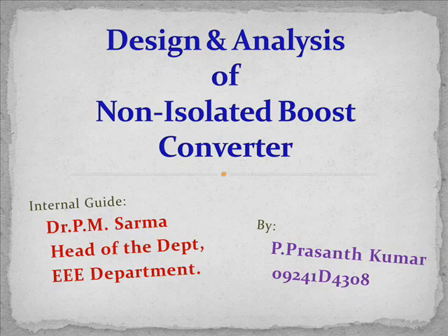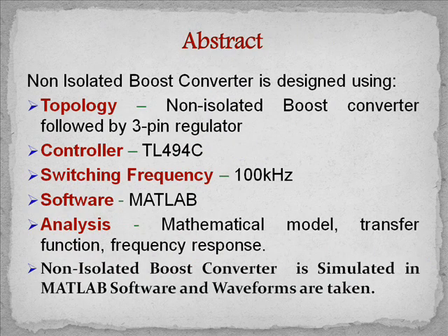My project title is Design and Analysis of Non-Isolated Boost Converter, and my guide is Mr. P.M. Sharma, Head of the EEE Department. The Non-Isolated Boost Converter is designed using the Non-Isolated Boost Converter topology followed by a 3-pin regulator. The controller used here is the TL494C, and the switching element is a MOSFET, with a switching frequency of about 100 kHz.